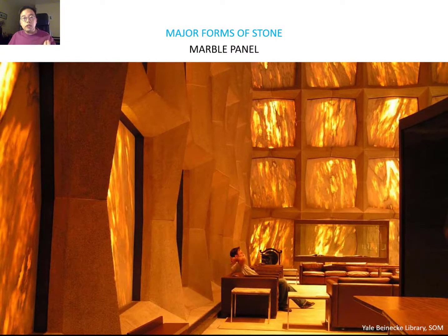When they use this thin marble cut, they actually diffuse lighting through this thin marble panel. So that's why when you get inside this library, the lighting diffuses from outside, and you can feel a totally different feeling from the outside. You can even feel the marble pattern, because the white part lets more lighting come in, and the darker part blocks more of the lighting.